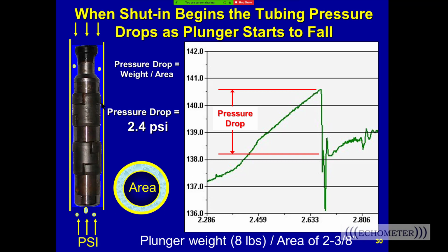But just coming up dry, it could come up dry for other reasons. It comes up dry because there's no liquid, which would be not enough afterflow. It comes up dry because it's not getting to bottom, which is a short rise. It comes up dry because it stops on some kind of debris or scale. So those are the three reasons I can think of, and there's probably more I can't think of right now. So you need to check it and make sure it's getting to the bottom.